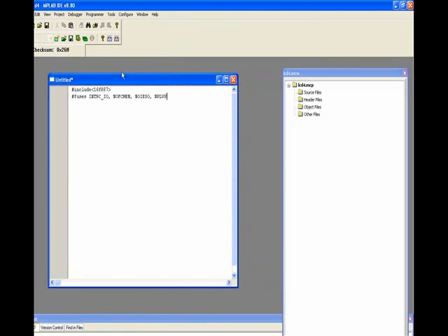You can do this in the configuration bits, which can be found under configure, or you can do it in code. Now we are doing it in code. This is telling the CPU that we are using the internal oscillator of the microcontroller, and the last part after the underscore means that since we are using an internal oscillator, the input and output pins can be used for any other thing. Okay, all right.